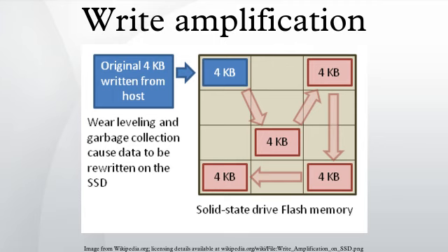no write amplification. The reason is as the data is written, the entire block is filled sequentially with data related to the same file. If the OS determines that file is to be replaced or deleted, the entire block can be marked as invalid, and there is no need to read parts of it to garbage collect and rewrite into another block. It will only need to be erased, which is much easier and faster than the read-erase-modify-write process needed for randomly written data going through garbage collection.